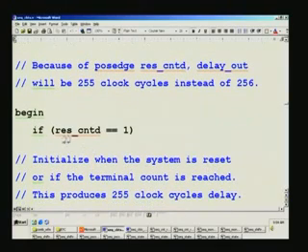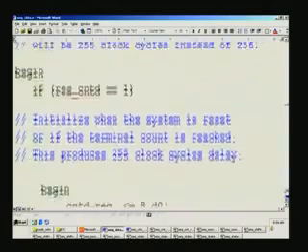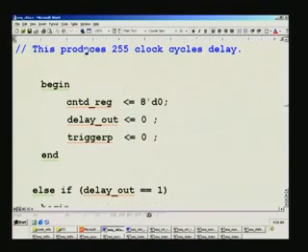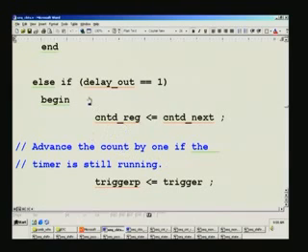So here we see that reset counter D equal to 1 is being checked. We are in the always loop at positive edge for the mono shot, and for that we are resetting here, and otherwise incrementing when delay out, which is already on, the timer is on.